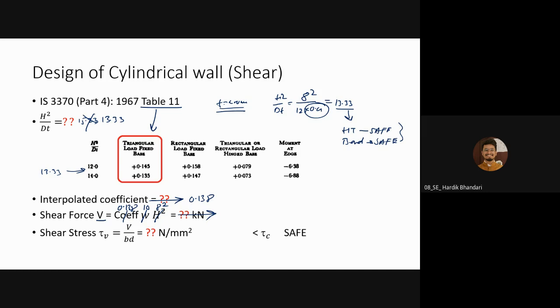88.32 kilo Newton. Now we have to calculate the actual shear stress. This is 88.32 into 10 to the power 3, the width is let us say 1000, and the capital D value we are taking as 400. We can take 40 as clear cover, so your small d will become 360. How much is the shear stress?